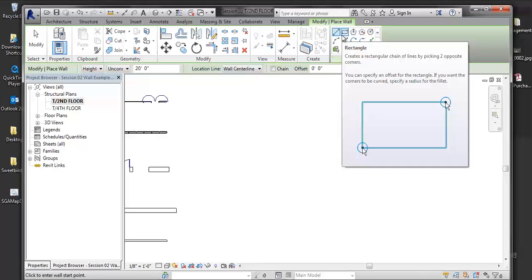Most of the time, if I'm doing the CAD space plan and I'm coming in and then bringing it into Revit and going to build my walls off of it, I'm going to do everything on center line, and then I'm just selecting everything and letting it populate. But then again, it's really dependent on what you're doing and what the level of detail is of the pieces that you're pulling from. Because it doesn't have to be CAD lines. It can be floor slab edges. It can be other walls. It can be pieces of millwork that I'm picking lines off of. It really can be anything that exists in Revit.